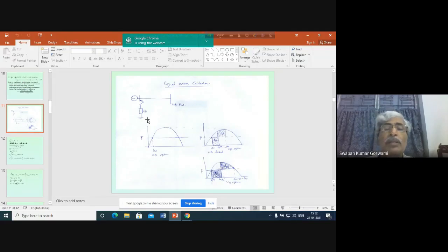That means as if we have applied a fault and we have to clear the fault, and the fault must be cleared before this critical angle is reached. That's why it's called the critical fault clearing angle, or sometimes the critical clearing angle. Here we have discussed an artificial situation, as if an artificial fault has been applied, but in reality, in an actual system, this type of situation may happen.